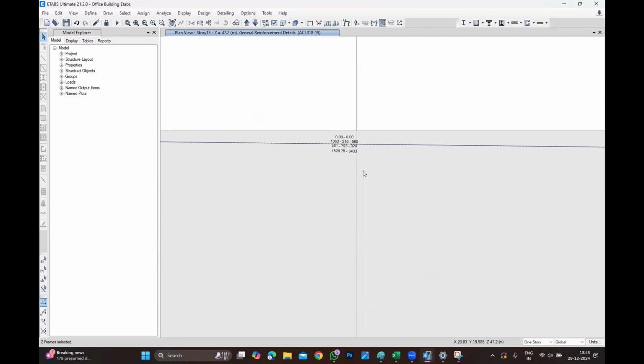This is the concept. When the beam fails under shear, it is demanding a number of legs. The legs you cannot provide unless you increase the width. You get a point? The beam fails under shear.